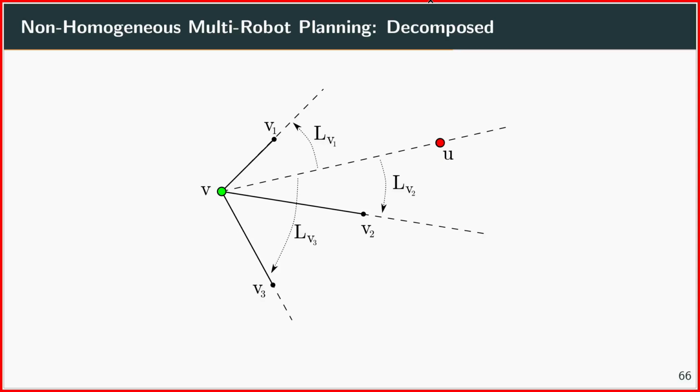And you compute the angles between this straight line here to the point and the angles to all the neighboring straight lines, and you just pick the one which minimizes this angle. So in this case here, it could be this one here, and then you just expand towards it. And so this basically combines this random sampling of RRT together with this exploration of M star.